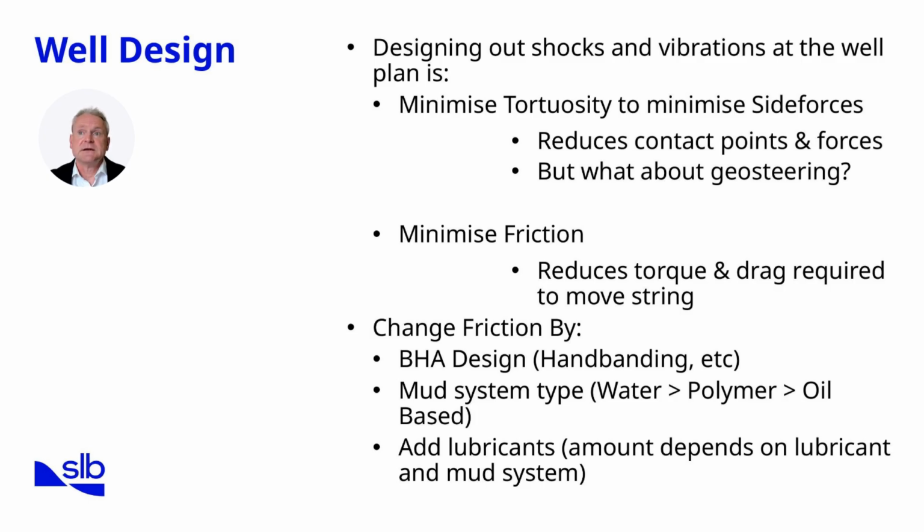Adding lubricants can further minimize friction, but their effectiveness depends on the base mud type. In summary, thoughtful well design, considering tortuosity, friction, mud properties, and assembly features, allows us to proactively minimize shock and vibration before drilling begins. With design principles established, we can now turn to how rotating equipment settings influence torsional response.